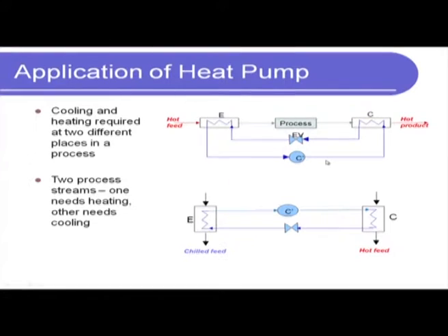It is compressed by the compressor, where it goes up to a higher pressure and therefore a higher temperature, and at the higher temperature it condenses and rejects heat and becomes liquid at the higher pressure still, and then you use an expansion valve where there is an isenthalpic expansion, where the liquid refrigerant at the high pressure is suddenly brought down through this expansion valve to a low pressure where it is typically still liquid or in the two phase region with low quality,